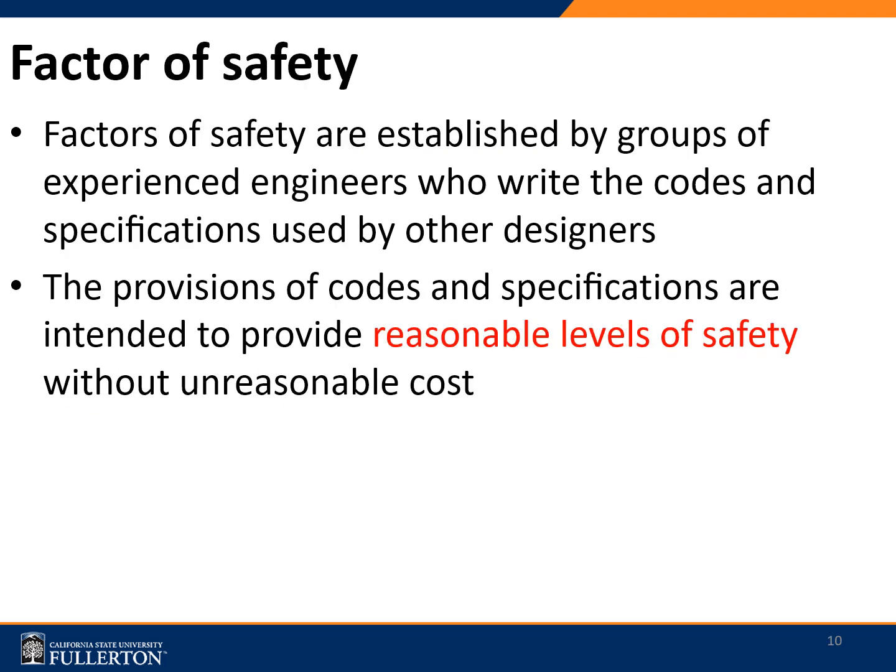Now the question here is which failure criteria are we referring to, or which failure point? Is it the yield point or is it the fracture point? If it is the yield point, we use allowable stress with respect to the yield stress. If it is the ultimate tensile strength or the fracture stress, we have to adjust the factor of safety depending on that stress value.